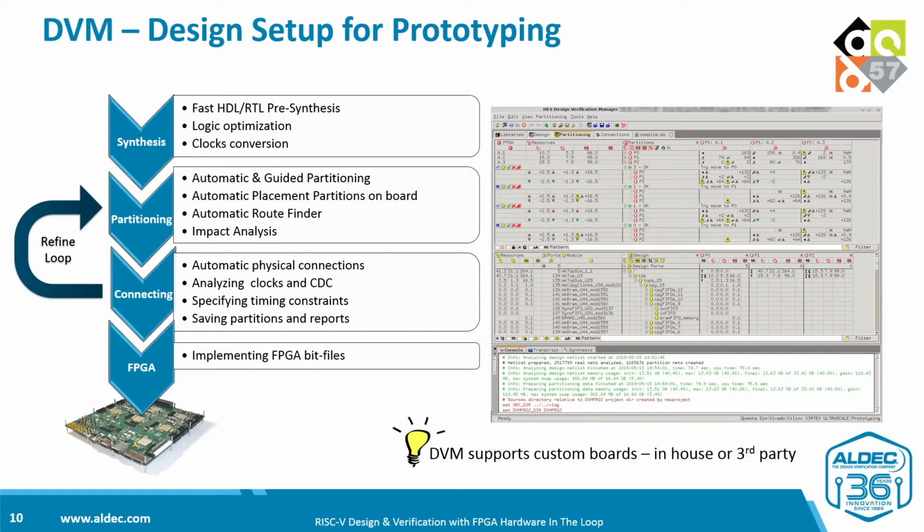The reason for having DVM prototyping separately is that it supports third-party boards. You can create your own board description file using SystemVerilog, and then with the board compiler you can import it to the DVM and finally use all the DVM powerful partitioning features exactly the same way as with Aldec HES boards.